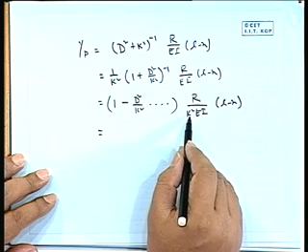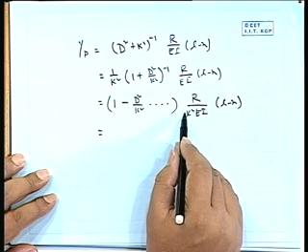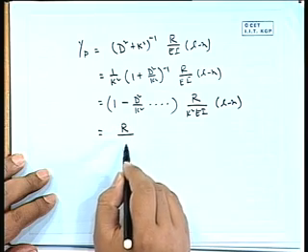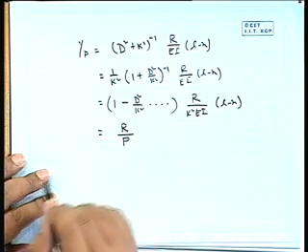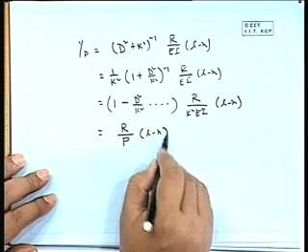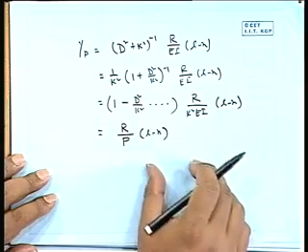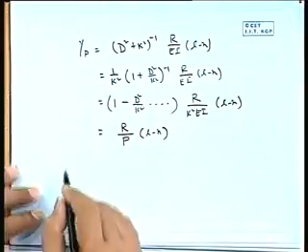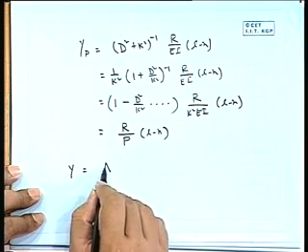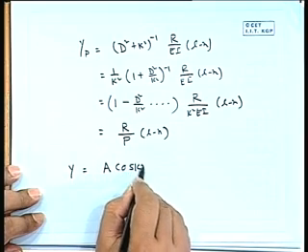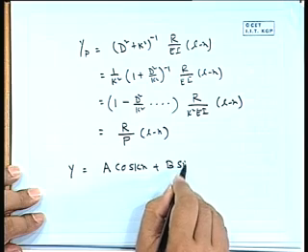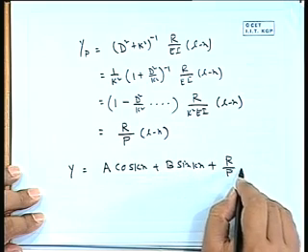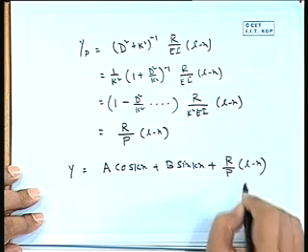So here k square equal to p by ei, so ei we can cancel, so we can write r, and here we can write p, and here L minus x, and it will be multiplied by 1. Other part if we take, we will not get anything. So y we can write the complementary part a cos kx, b sin kx, plus r by p L minus x.